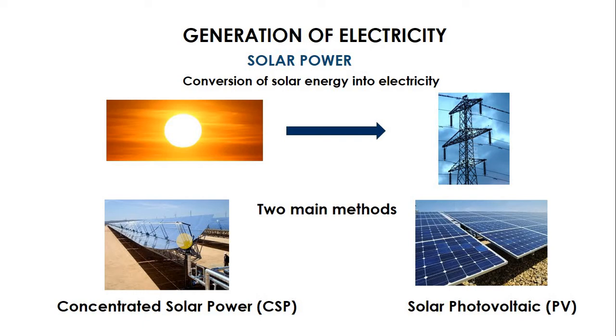The thing about water is that, yes, we can use the concentrated heat energy from the sun to boil the water, but water has a very poor heat retaining ability, which means that when the heat drops, the steam that was being produced will no more be produced. So slight fluctuations in the heat energy from the sun may cause the steam that is being produced to also fluctuate. And once the steam level drops, the turbine cannot be driven again, and there will be no electricity.